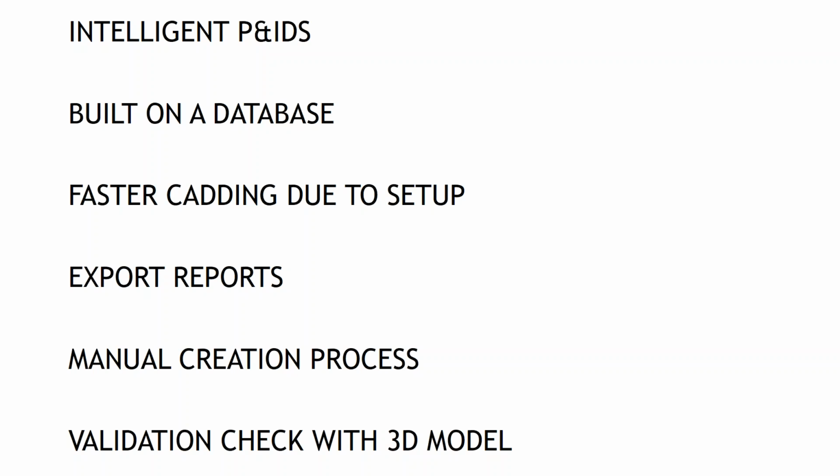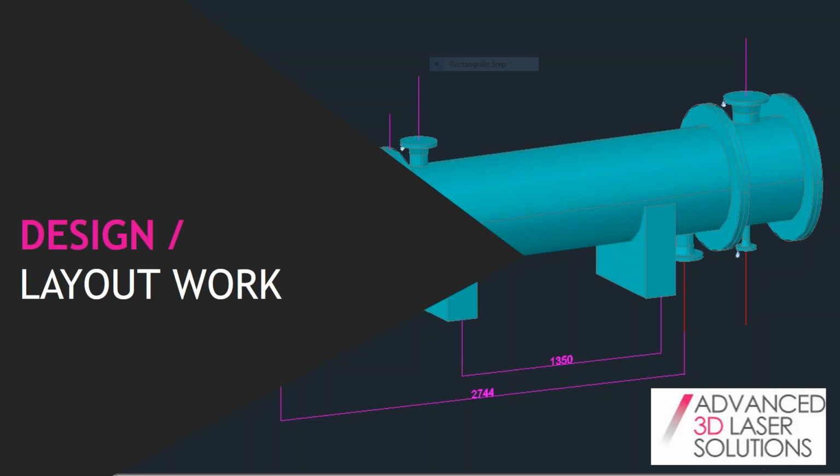Also, when you add in valves, it automatically breaks the line so that you haven't got that line passing through it. And for a company like us that specialise in doing this almost as a day-to-day job, we've got 3 people here that all they do is create P&IDs. They create P&IDs from either doing site surveys or from a similar project like this pharmaceutical one, where they're using the 3D model as a survey method. So we've created this really accurate 3D model, and they're using that 3D model to work out where all the lines are going.